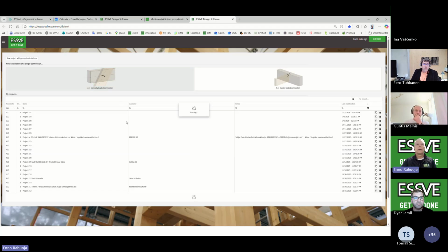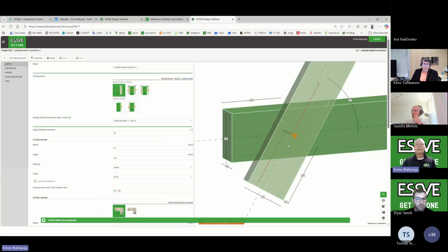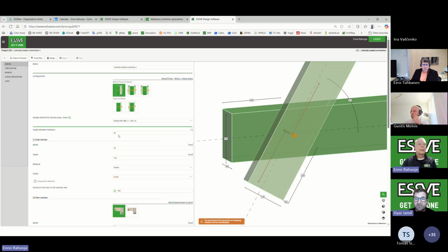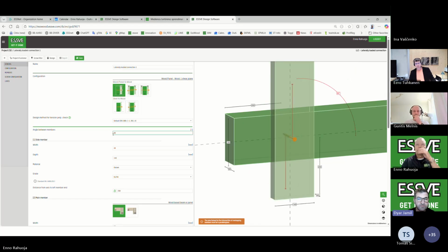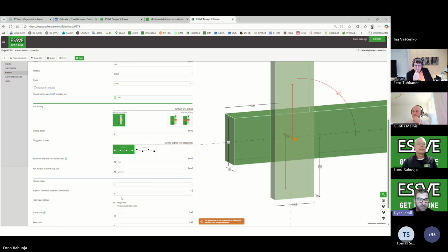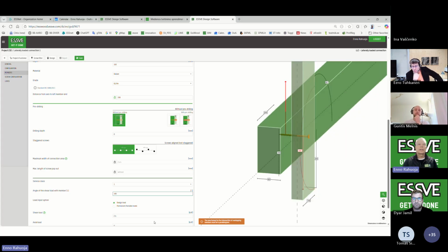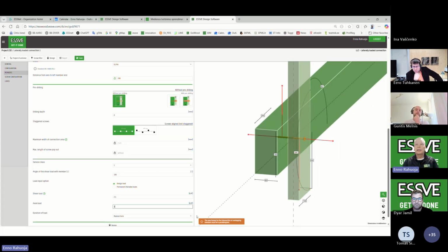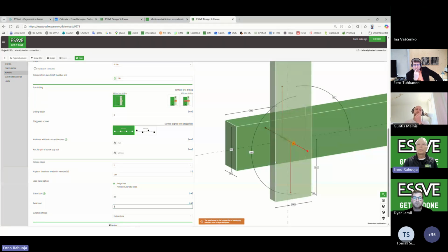And when I go here on the calculation side, you see this secondary beam. If you go down, if you go up more, you can change here that shear load angle, whatever you want to have. Like we had 180, then you can have the load this way. And as you see, there is no axial load at the moment, but if you give a value here, then you will also have the axial load available. And you build up your parameters how you want to have them.